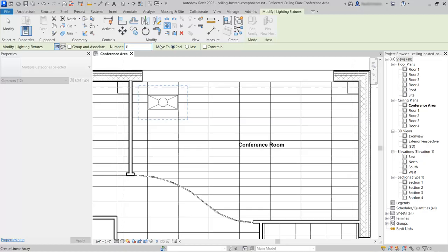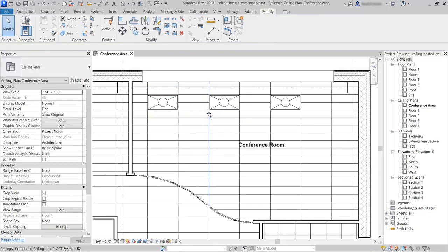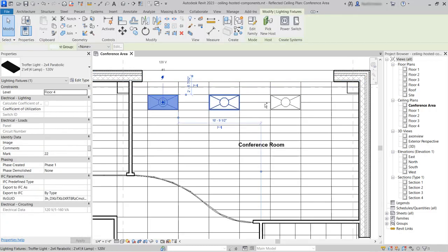So now we can go down into the view, and we'll click on the vertical grid line on the left for the start point. And then we'll leave a gap of 1 tile here, so we'll move across to the second and then click. And then we'll get the 3 light fittings arrayed across the room. So now we'll do this in the opposite direction. So we'll select these light fittings, and I'll just use the Control key to multiple select them.